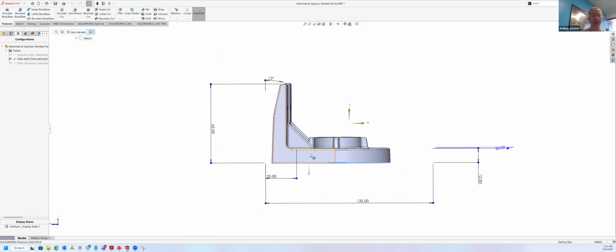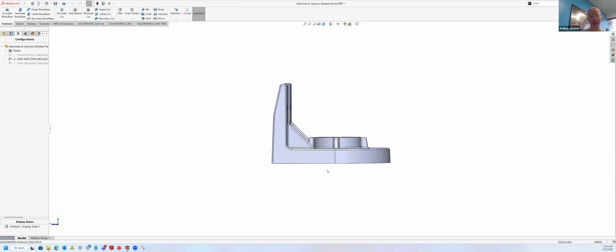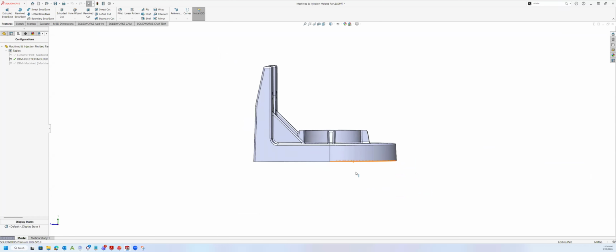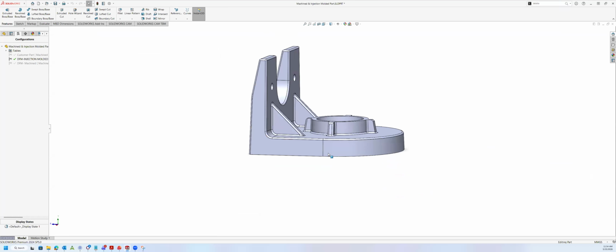Is there a reason why the bottom face doesn't have a radius? We could definitely put a radius on there. At the moment, I just thought it was unnecessary. However, now that I think about it, it might help out when it comes to reducing stress concentration and helping the part release when ejected out. So good point.